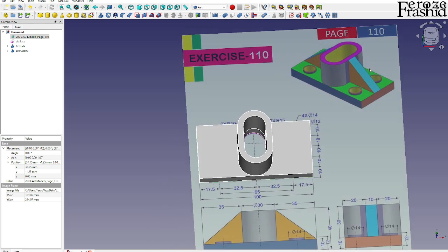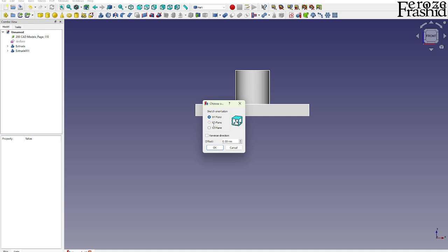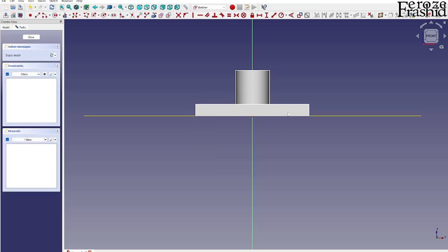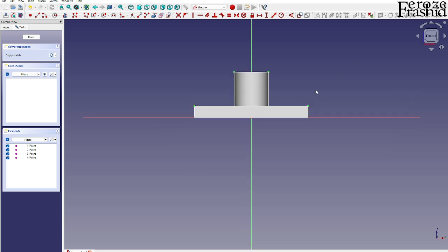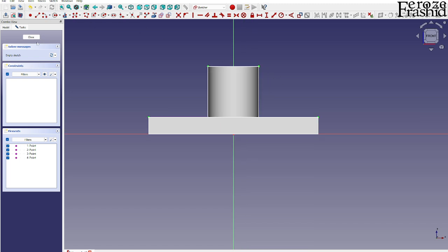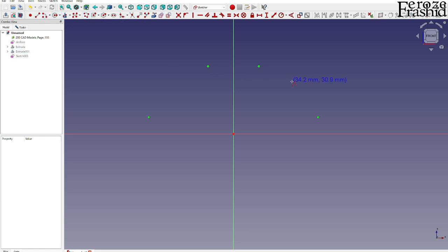Anyway, now we want to create these two triangular reinforcing corners, and that would be on this surface, XZ plane. Let's draw a sketch on XZ plane, and it would be simple. What I want to do is take this line and this line, obviously this line and this line. So now I want to add them up, just like that.